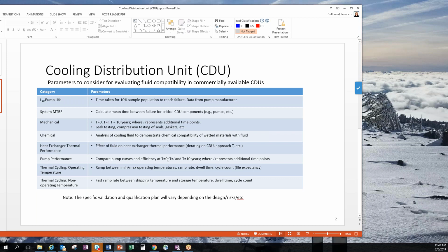And that's why, anyway, it's not easy to figure out how long it's going to last. And the biggest problem with things not lasting a long time is mistakes that you made during the design process that you maybe didn't notice, like putting the pump in a bad spot so the inlet conditioning isn't good, or, like I said, it's cavitating under certain circumstances. There's a lot of mistakes you can make.